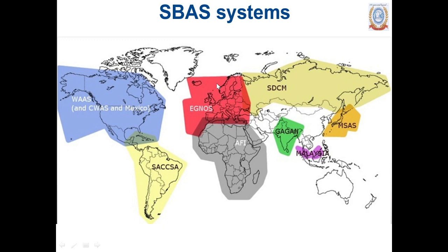So more people are comfortable with GPS, then DGPS they call. DGPS is differential. The differential means you will have a reference system kept outside. Now, if you have the reference system also incorporated into satellites, which are geostationary, then it is called an SBAS system, augmentation. So the augmentation can be from the ground control by you, or it can be made available in a satellite system itself, so that you get reference corrections from the satellites. Not in the same GPS satellites, it is all separate reference satellites. Those satellites will have a coverage.